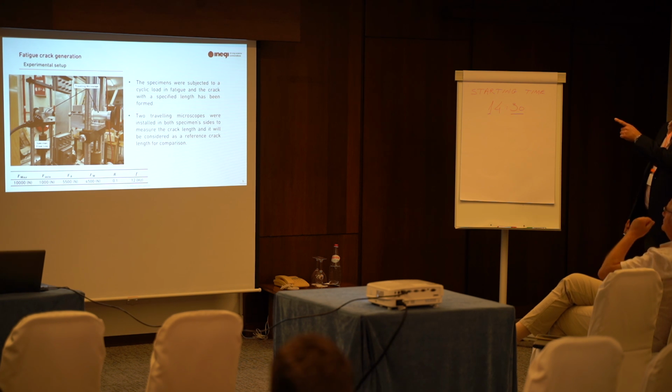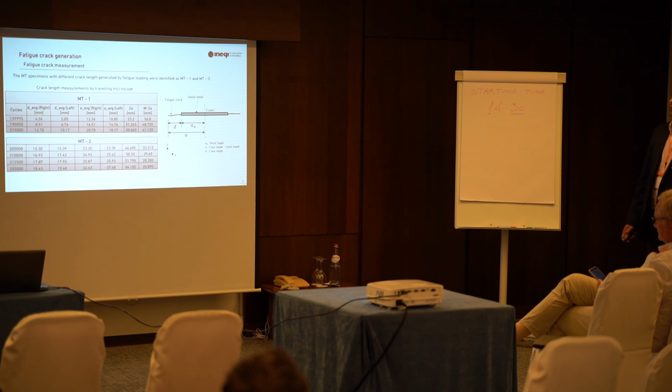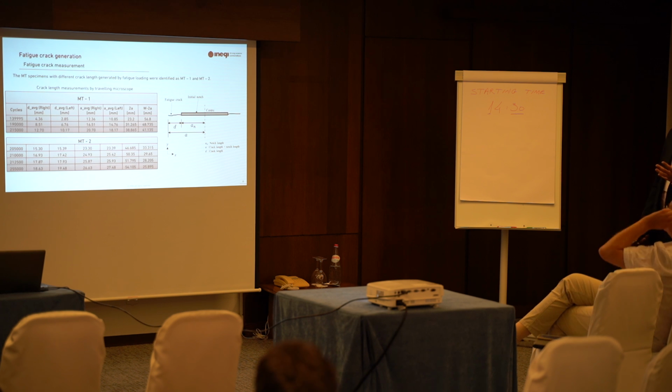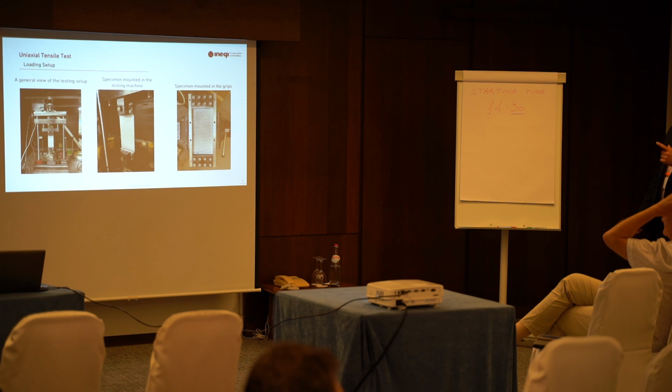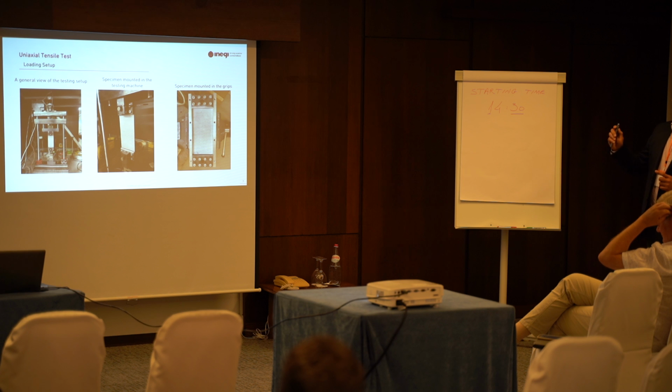The crack was measured by two traveling microscopes, one on the front side and the other on the other side of the specimen. We reached the crack length that we decided to have. Two specimens were identified: MT1 with the long crack and MT2 with the short crack. So the fatigue test has been done, and the desired crack length was acquired, measured and documented.